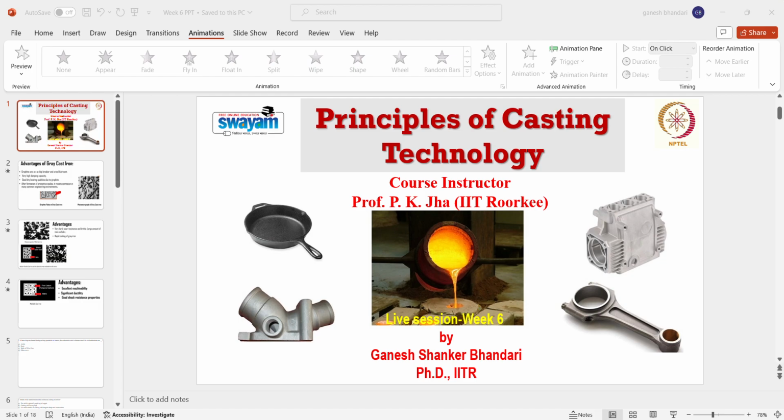Only iron carbide is there because you are not providing sufficient time. When you melt it down and put in your graphite or carbon percentage of around 4 to 5%, the typical concentration of cast irons, it will be in the form of iron carbides in the beginning. At higher temperature it will form iron carbide, and when you cool it down, that iron carbide will decompose into iron ferrite and your carbon structure. Fe3C will get converted into 3 Fe plus carbon.